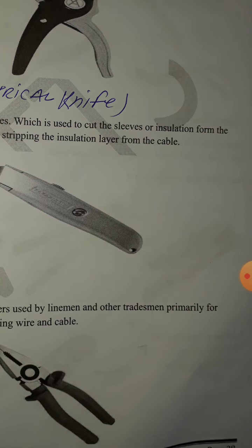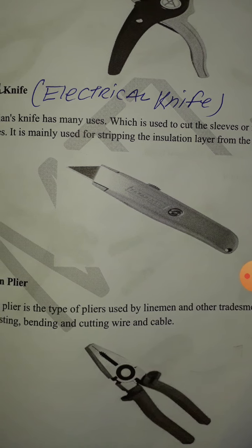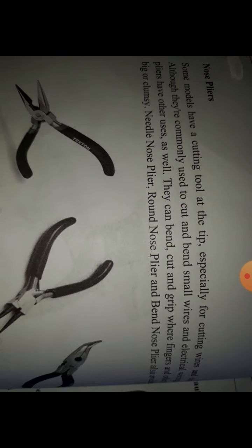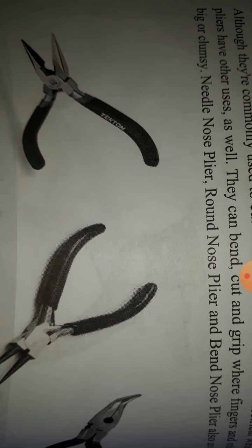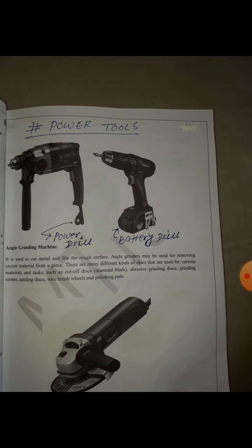Combination plier. Okay, this is combination plier. So plier is also needed to catch some equipment and cut some wires, and that is done with combination plier also. Okay, and notch plier is also used the same way, we can use it for cutting purpose, and when a wire inside a pipe is not possible to come outside, you can use notch plier to pull it also. Okay, notch plier. And hand tools is completed.